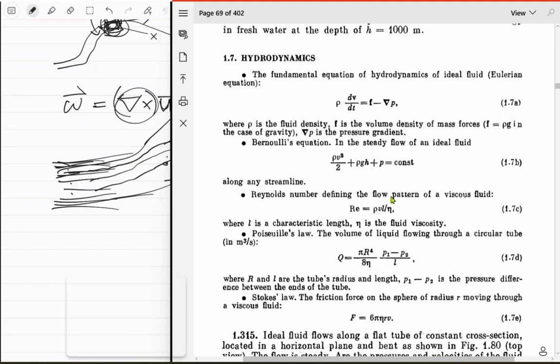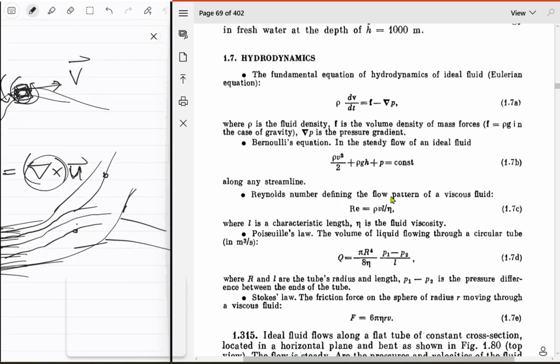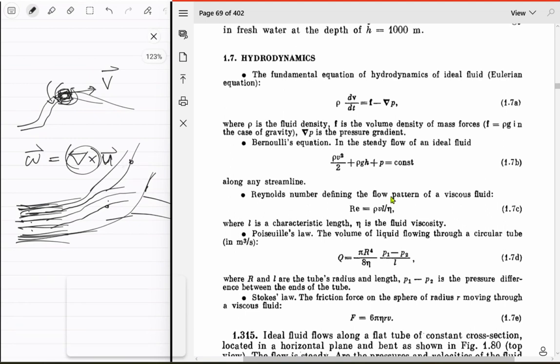Look at these, they have the same pressures everywhere, right? There is gravity, and because of that the pressures are different, I know that. But come on, is that so complicated? No, right? Just assume the tube is very thin, and then you can just do it. Yeah, that makes sense. And even if the pressures are different, you can still apply Bernoulli's equation along one streamline, and then you can trace back and compare how the pressures change, right? So that you can still apply Bernoulli's equation for these 2 points.